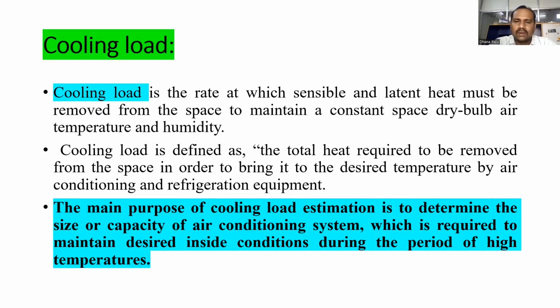Whenever the summer period occurs, automatically we have higher temperatures inside the space, but people feel very comfortable at design conditions like 24 degrees centigrade and 50% RH. These conditions of air can be achieved by removing the excess amount of heat present in the space. For that, we need to evaluate how much cooling load there is.